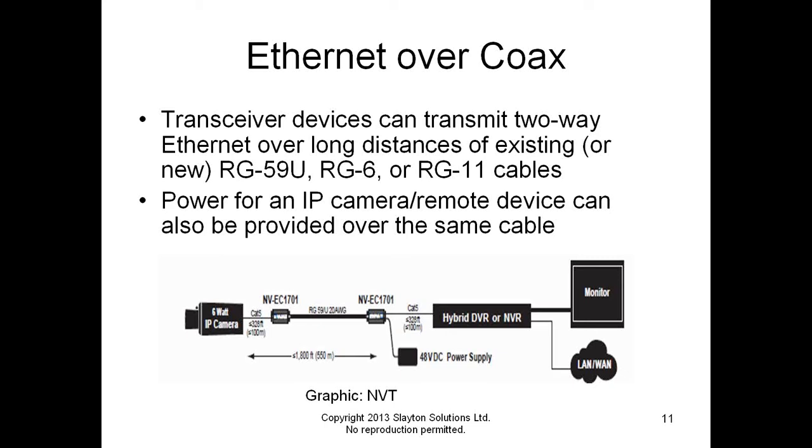Now, notice that the power supply is on the head end, which is kind of in the middle of the screen, and we're pushing the power and the Ethernet through the coax cable to the transceiver device on the far end, which is then hooked up with Cat5e jumper cable out to the camera, in this case a 6-watt camera that we're powering.